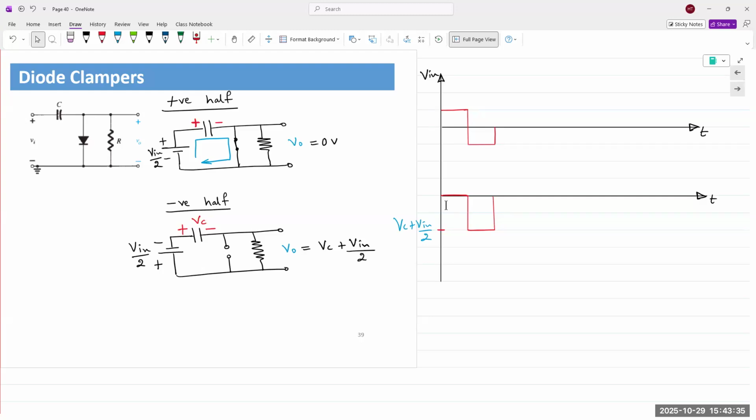We could create the clamper circuit, and if we applied a low enough frequency, let's say half a hertz or even a quarter hertz, which is possible with our function generators, we would see a slope because it's not charging fast enough. We could increase the size of the capacitor and lower the frequency to less than 1 hertz, and we would be able to see a charging and discharging slope, which is definitely possible.